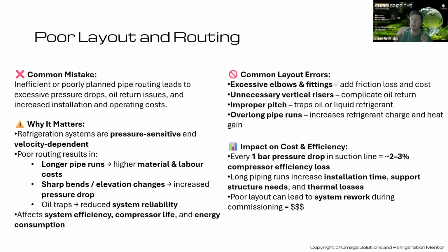What we don't want to do, if you have a building, is constantly step down along and step back up around beams. For example, if it's an old building and it's got a low ceiling, try and route it so maybe you go to the outside of the building, run round, back in. Can you move the plant? Can the compressors be moved to another area of the building? All these things need to be looked at as a strategic design early on in the stage of it, rather than once you've gotten to site as the pipework's being installed there and then.